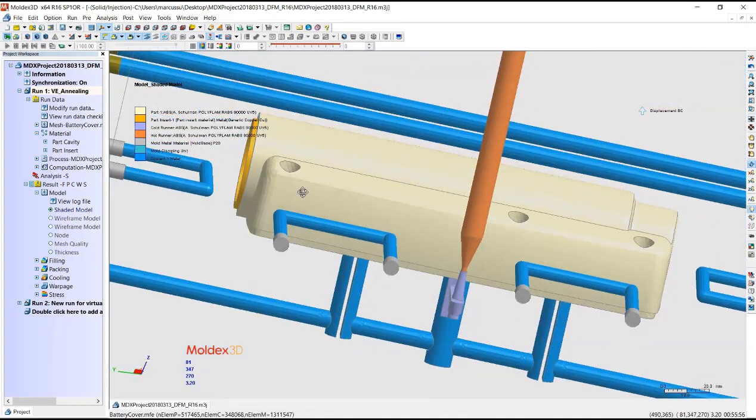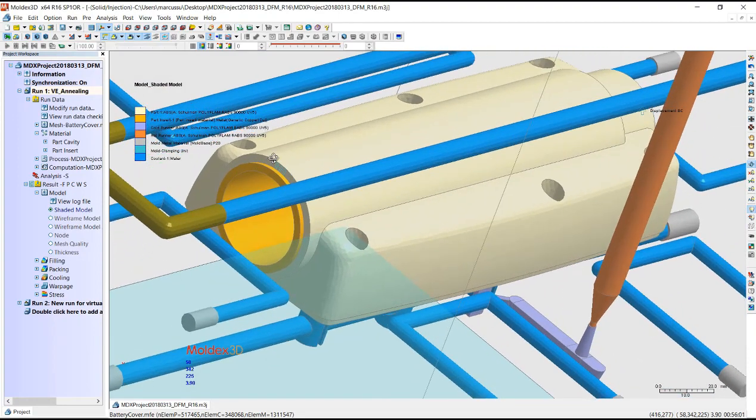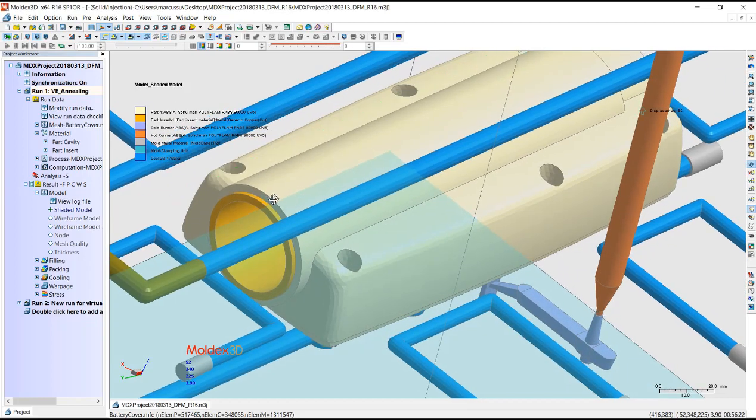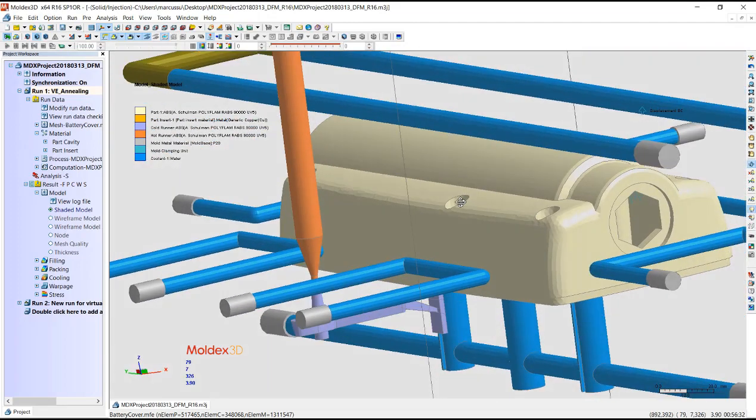Because if you fix too much boundary condition, the part cannot move, and it still needs to deform due to the annealing process. So it will generate extra stress because of some fixed positions. Therefore, I try to minimize the fixed boundary conditions. Not all three, but some of them are fixed. This helps the stress solver converge.